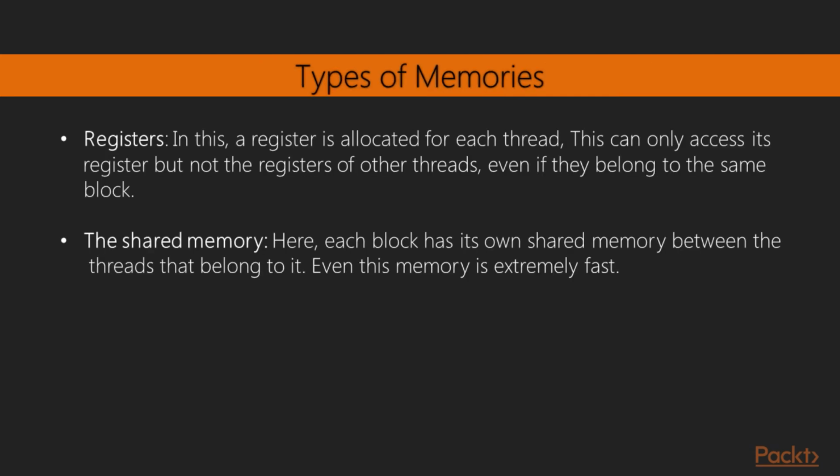A PyCUDA program, to make the most of available resources, should respect the rules dictated by the structure and the internal organization of the SM, which imposes constraints on the performance of the threads. In particular, the knowledge and the correct use of the various types of memory that the GPU makes available is fundamental in order to achieve maximum efficiency in the programs.